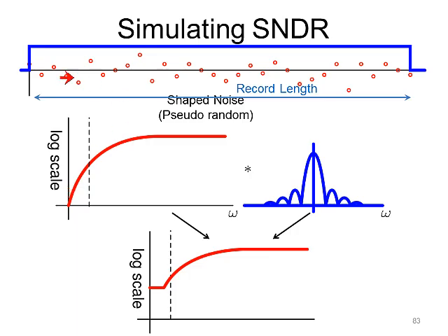Now, because of windowing, the spectrum of the windowed sequence is this spectrum convolved with the sinc because of the rectangular window. And as you can see, when you convolve this spectrum with this spectrum, you get this because, for instance, energy here will leak to the side and fill up the in-band bins. So you would expect to see that the in-band spectrum is filled up with leakage from out-of-band noise rather than fundamentally from the ADC itself.